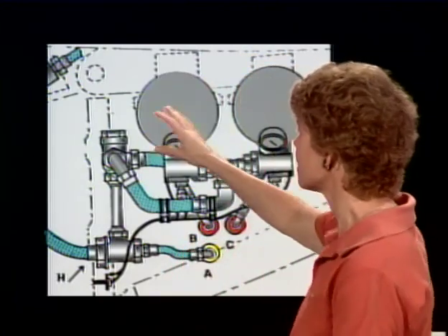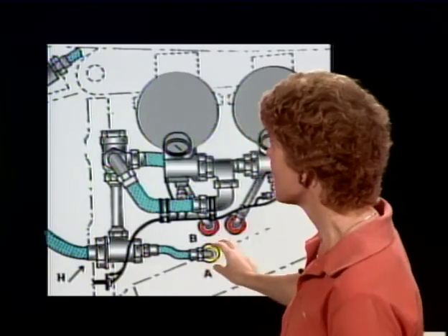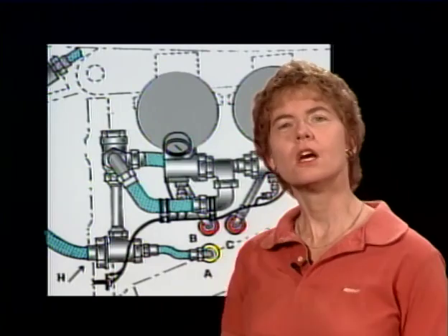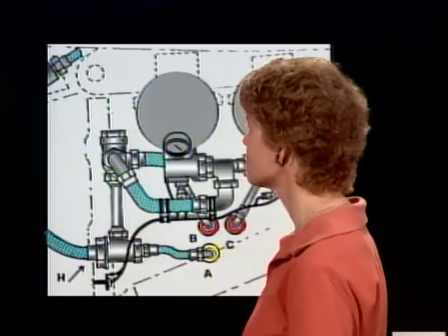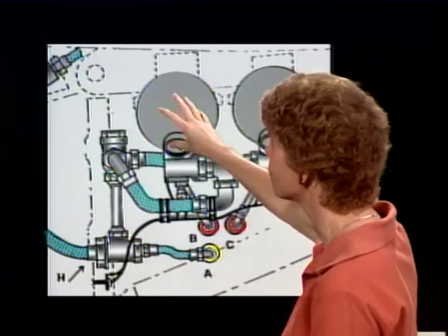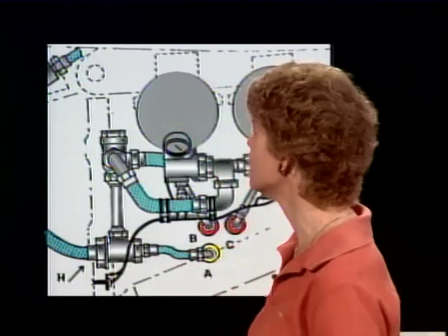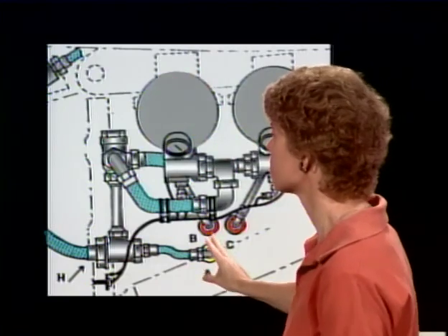in order to put out a fire. On the other hand, each of these fire extinguishing bottles has its own red indicating disc that will tell you if there has been a thermal discharge, meaning an overpressure discharge of a built-in fire extinguisher system. If either one of these bottles overpressurizes because of excessive heat or whatever, it will blow out its own red disc, and that tells you that there was a thermal discharge of that built-in fire extinguishing system.